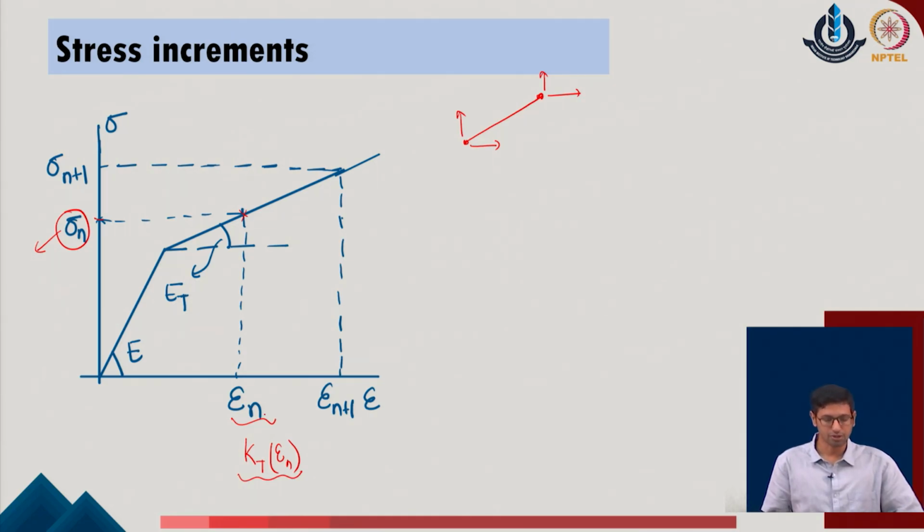and with respect to the given system, now the simple load, any kind of increment which is defined in the given stress component of the system, if we define this increment value, say d sigma on the given system. So, we realize that from this point the system will move to a new point which is sigma of n plus 1, and now this new point will be located with this constant slope.